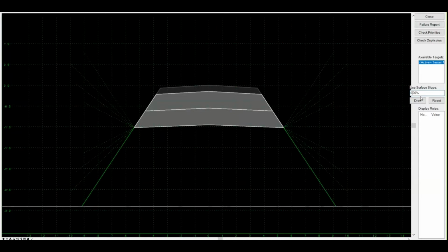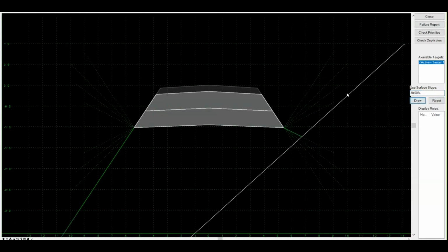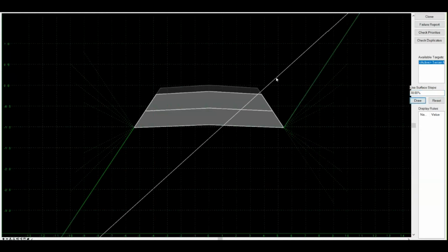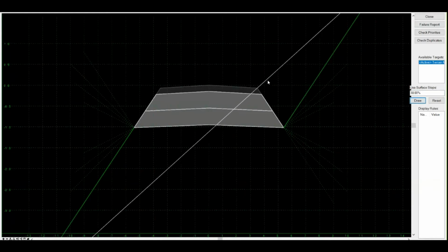And suppose it's a hilly area and you want to give a certain slope value to your ground, I'm taking a 30% value and clicking on draw. Now there will be different behavior for your end conditions. One section is coming in filling, one section is coming in cutting, so both slope lines are now different. You can check this even within this testing window.